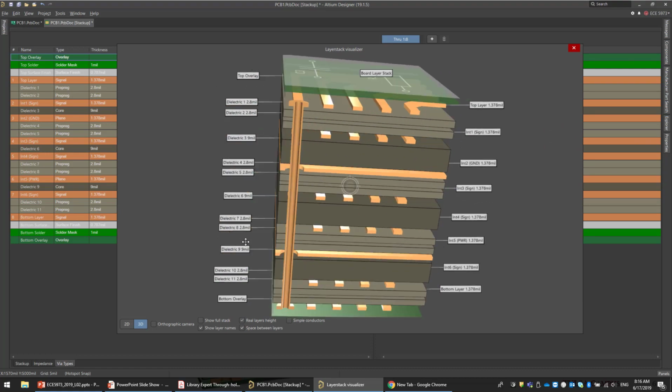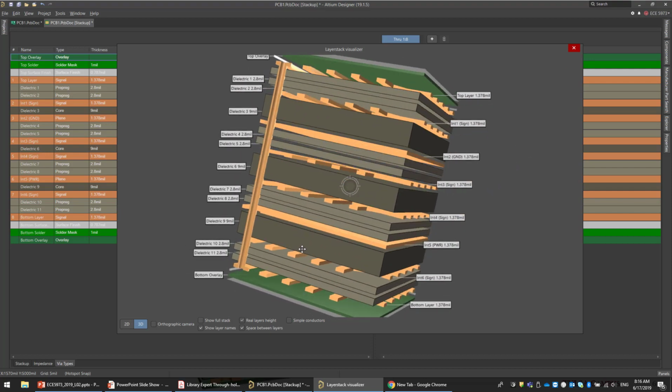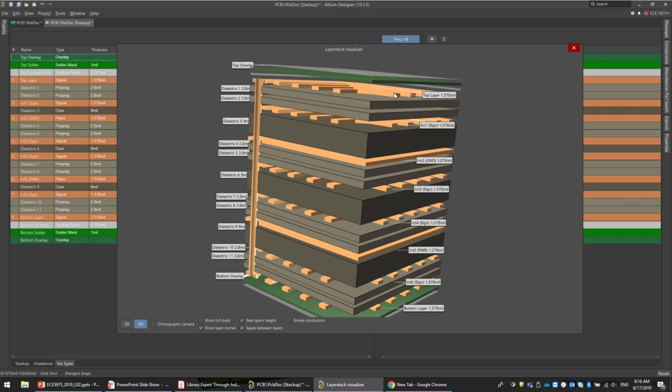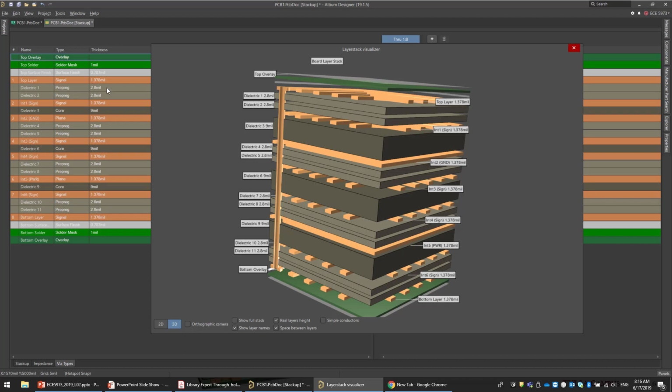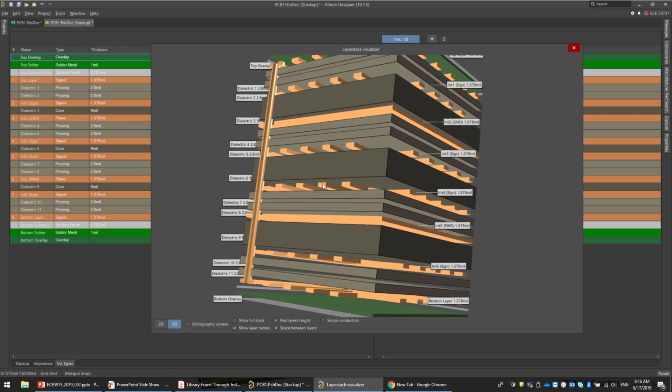And this via goes through layer 1, and here we have what we talked about earlier. So we have the cover layer, then we have 2 sheets of, let's see, what sheets did they use? So we have prepreg 2.8 mil and 2.8 mil, 2 sheets of dielectric or laminate material. Then we have a signal, another layer in here. Then we have a core, as we can see in here, it's 9 mil. Then after the core, we also have 2 dielectric layers or laminate layers with 2 covers on the top, constructing the cover clad here. And then we have another core, 9 mil, same thing. After that, we have cover, 2 laminate, then we have a cover, we have a core, and then the same thing. So 8 layer, we have 3 cores and 3 cover clad layers as well.